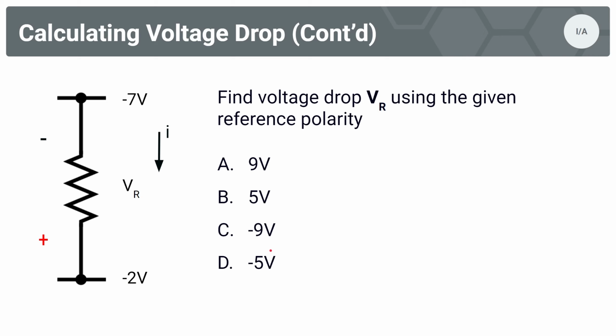We're almost there though. Remember, we need to apply our sign. So if our difference in volts was calculated to be -5, but we decided that the sign of the voltage drop is also negative, we need to take the opposite value of -5, and that's 5. So our answer is B, 5 volts. The voltage drop across the resistor is 5 volts.